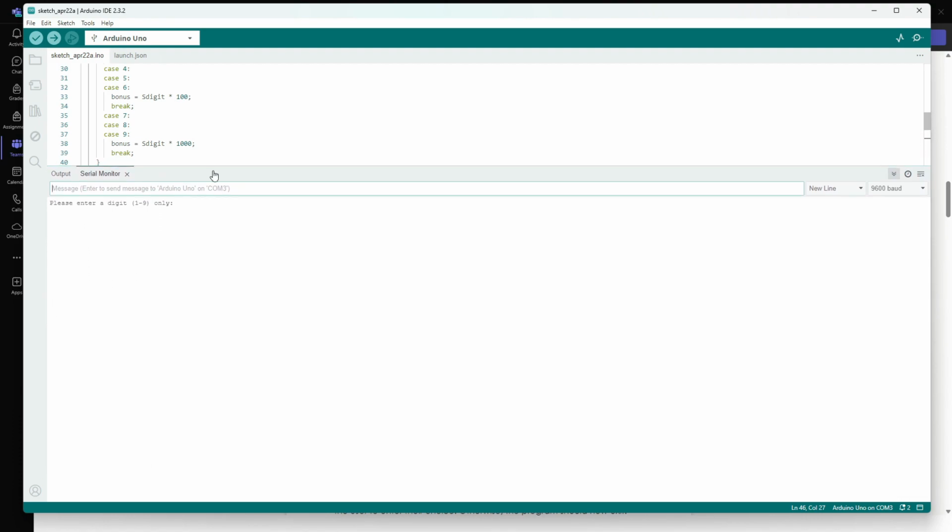But what is Serial Monitor? The Serial Monitor is an essential tool when creating projects with Arduino. It can be used as a debugging tool, testing out concepts, or to communicate directly with the Arduino board. We can find that Serial Monitor on the top right of our monitor. Just click that and now test the program.